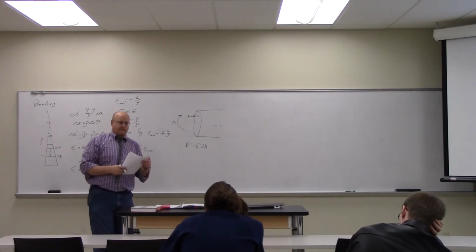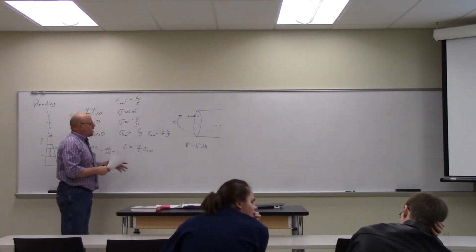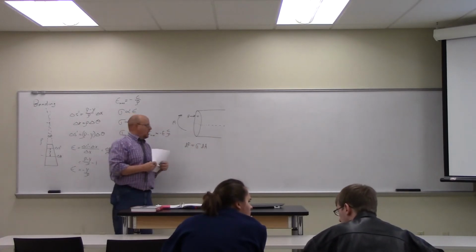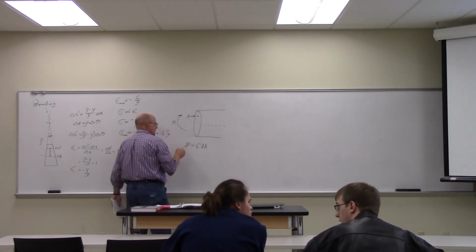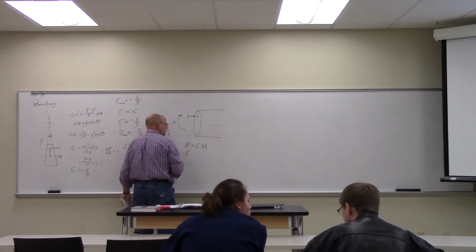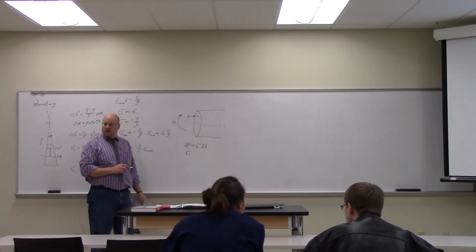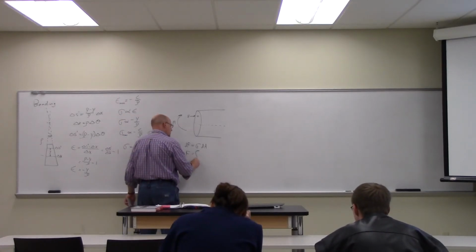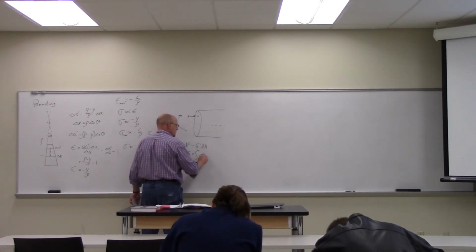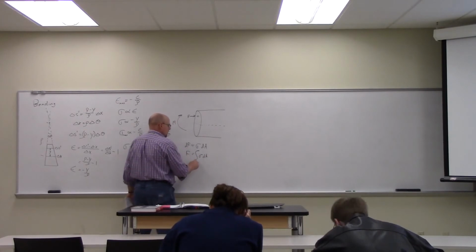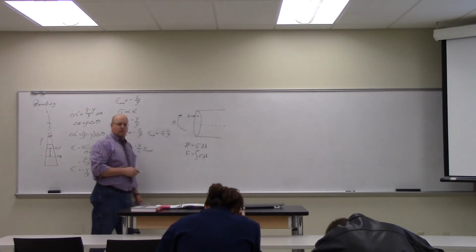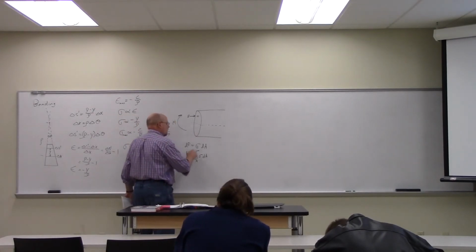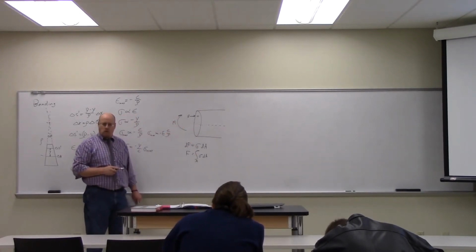Everybody good? Okay. So, element of force acting on that bit, sigma dA. But I really care not just about that force, I want to know what is the total force acting on that end face. So the total force is the integral of sigma dA, from the bottom to the top, over the entire area of that end of the bar.